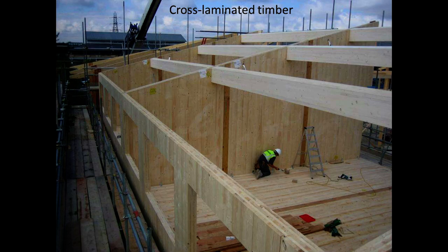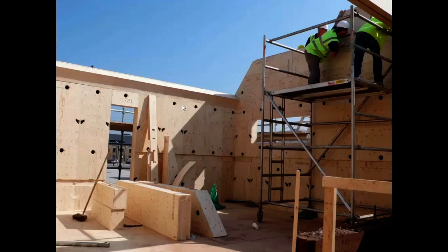This particular process is called cross-laminated timber. Timber has a kind of grain, a directionality. So if you laminate one layer in one direction, you laminate another layer in the other direction, and so on, you build up a very strong piece of timber. So these are load-bearing walls, modern load-bearing walls.